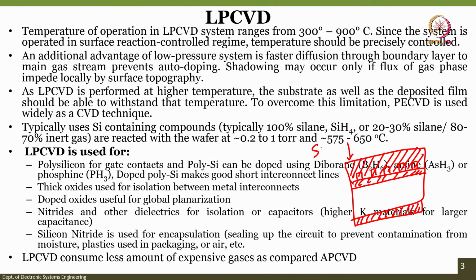This is your SiO2, this is the micro heater with nickel as the metal. Then this one is your SiO2, this one is silicon, this one is your SiO2, right. In this case what will happen? What will happen if I have nickel as the micro heater material and I want to deposit SiO2 using LPCVD, what do you think will happen?